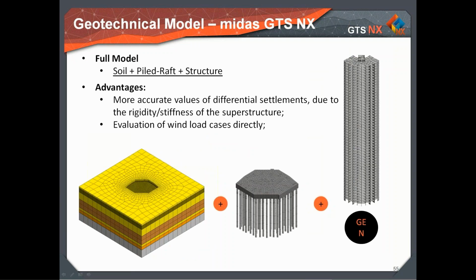Some numerical models of building foundations are made only by applying load or pressure at the base of the columns. It is like retrieving the highest values for each column from the structural team and applying them directly to the model. This might neglect the redistribution of loads in the superstructure and its stiffness or rigidity, as you wish. So those results differ from the real behavior of the structure, showing higher values of differential settlements.